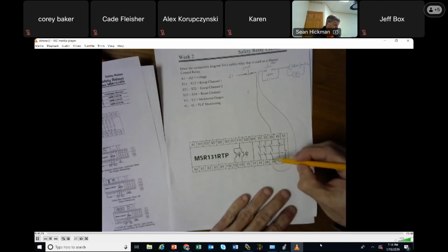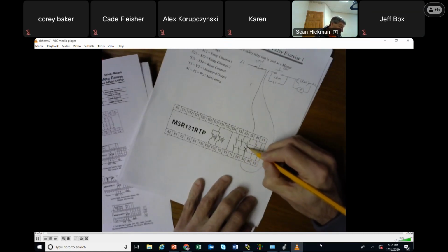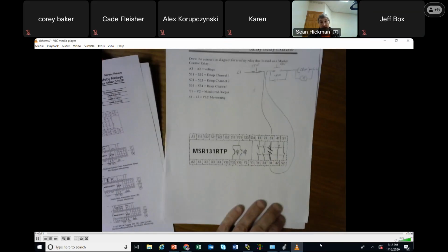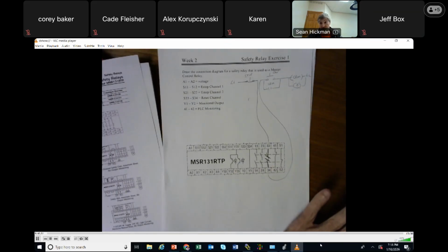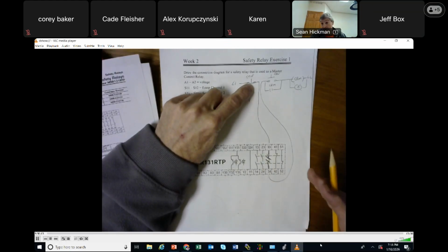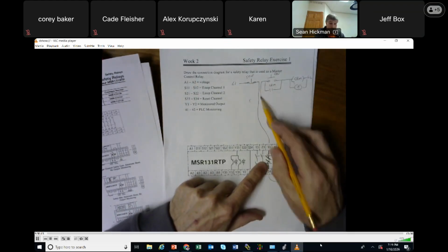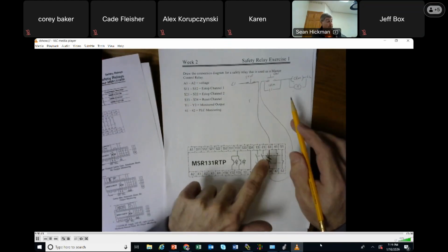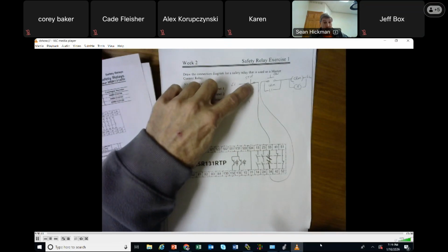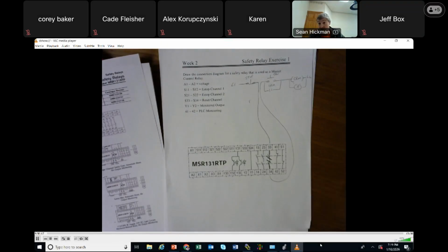And remember, all you're thinking right here, everybody, is that this is a normally open switch that's going to shut when this safety relay is on. So now I've got two ways to stop this circuit, assuming that this is armed and this is true. I could hit the stop button and it would turn it off like it normally does. But if I hit start and it was on, if I killed the safety relay, that would also open it up as well, okay? So do you agree that I now can open up the circuit here, or I could open up that circuit? On a scale of 1 to 10, does that seem reasonable? Turn the safety relay off or hit the stop button.